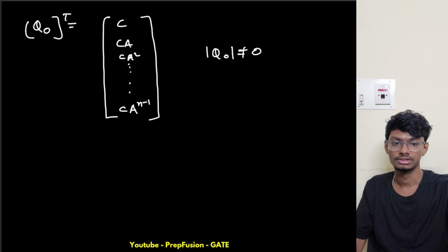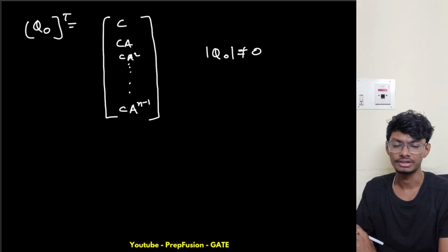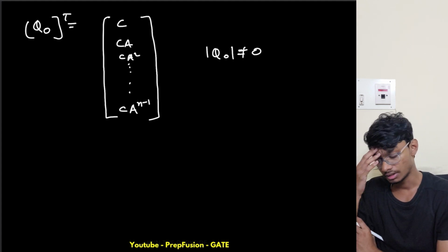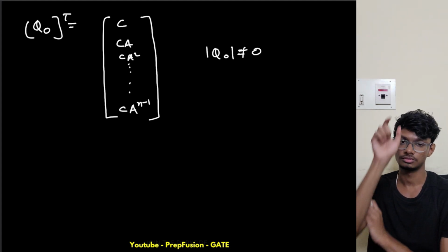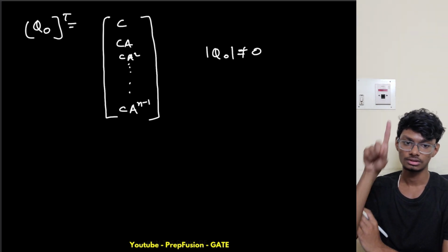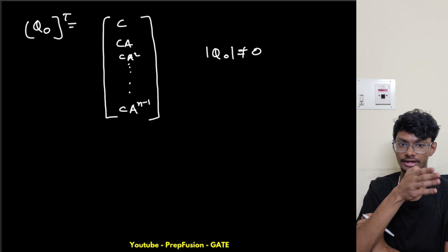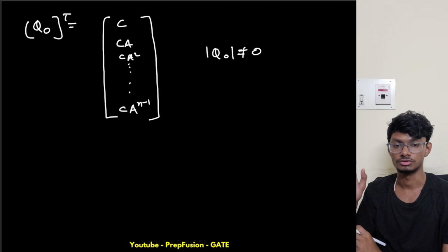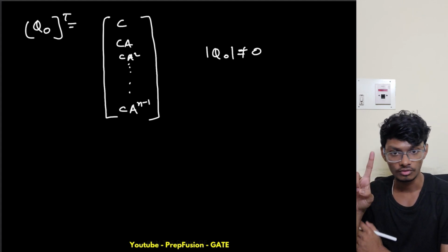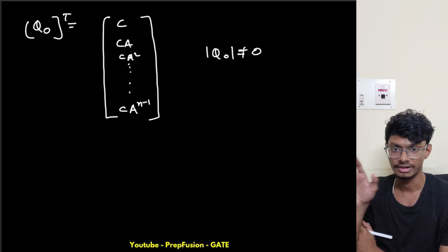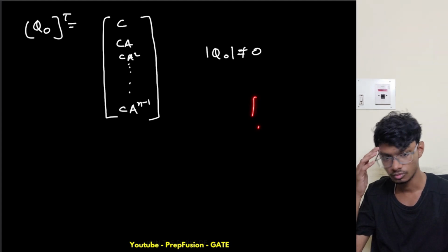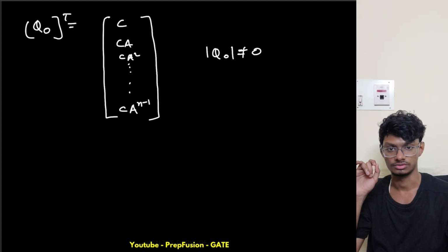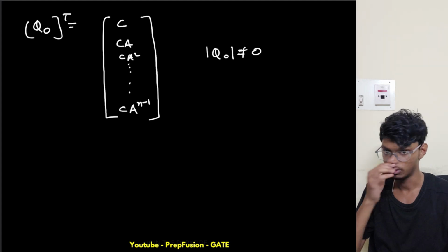Now what does Gilbert give us? Gilbert again has two rules, one for non-repeated distinct eigenvalues, basically for independent eigenvectors, and another one for repeated. So for non-repeated eigenvalues, the column of the C matrix corresponding to each eigenvalue should be non-zero. So each element of the C matrix should be non-zero for non-repeated eigenvalues. Okay, if I have two rows in C, at least one element should be non-zero. So yeah, that I explained in that lecture.